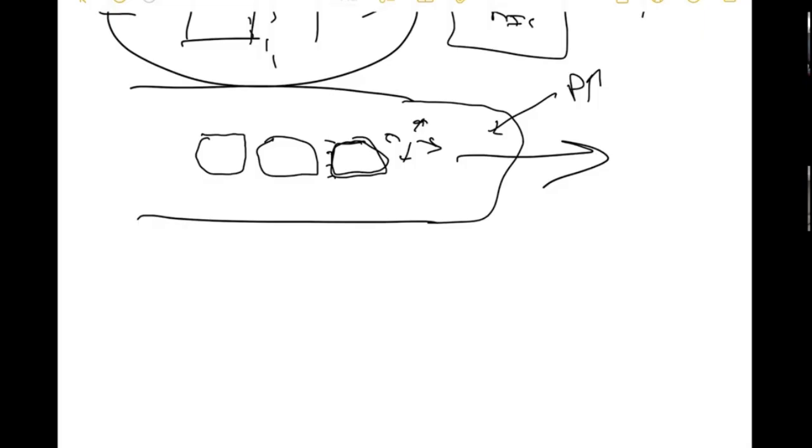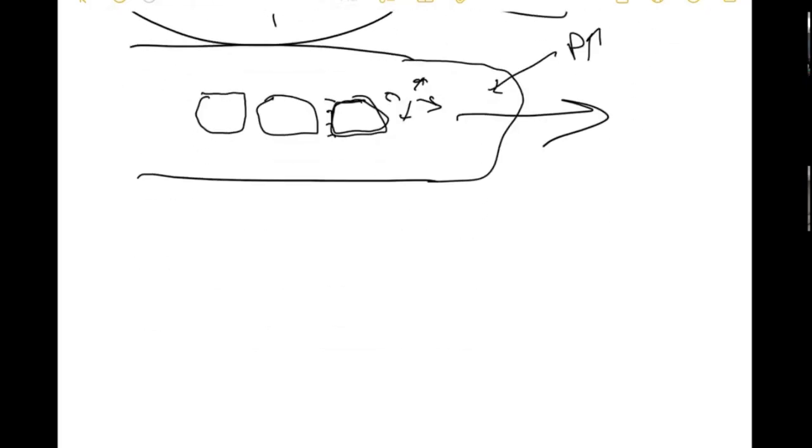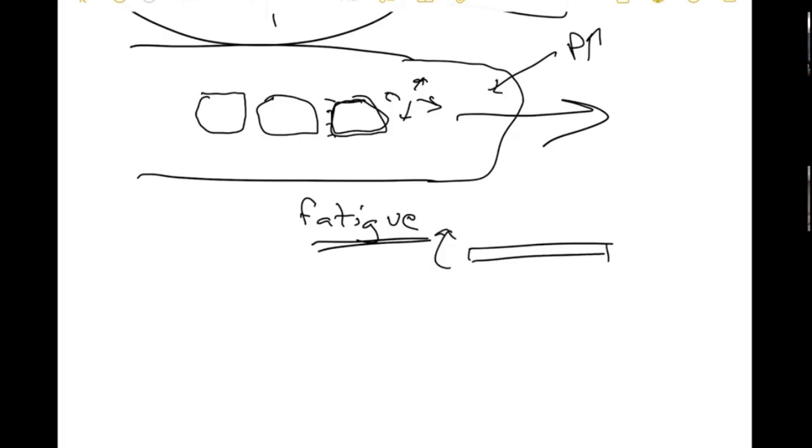Okay, so this was a big thing. There's all kinds of interesting history, and it took quite a bit of time. While we're here, this is typically not a single loading. It's called fatigue loading. Think of a paper clip. That's the perfect example. You know what a paper clip is, right? You may have one on your desk. Just bend it between your fingers. Just flex it about 12 times. It will break. That's an example of fatigue loading.